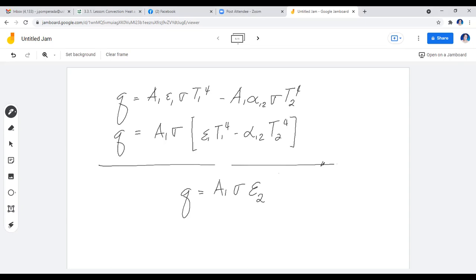So now your formula, which is actually simple in itself, is made even simpler if you're going to have this particular formula now used. So this is the formula that will be used in the solution that will be shown to you as shared in the slide. So we will go back to our slide. So take note of the formula: area, the Stefan Boltzmann constant, the emissivity at the surrounding temperature, and the two temperatures. Temperature of the material, the tube, and the temperature of the surroundings, which is the furnace.